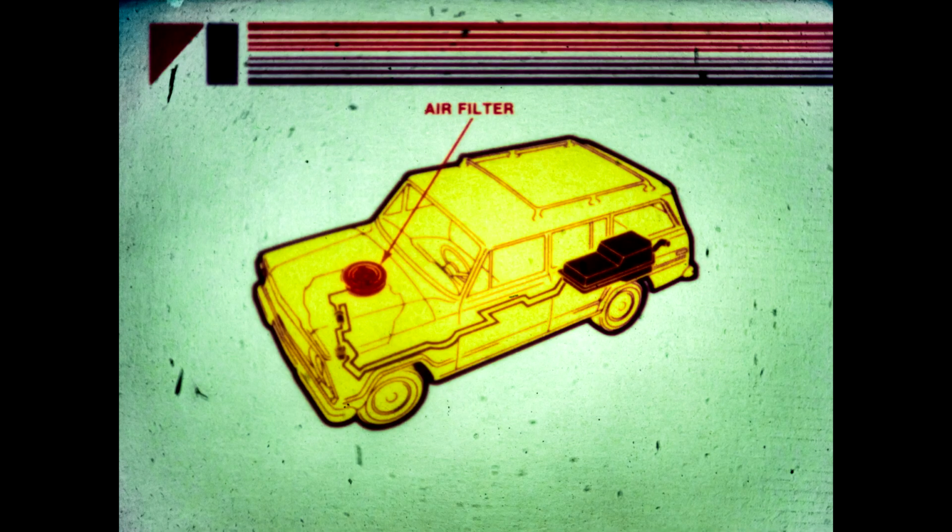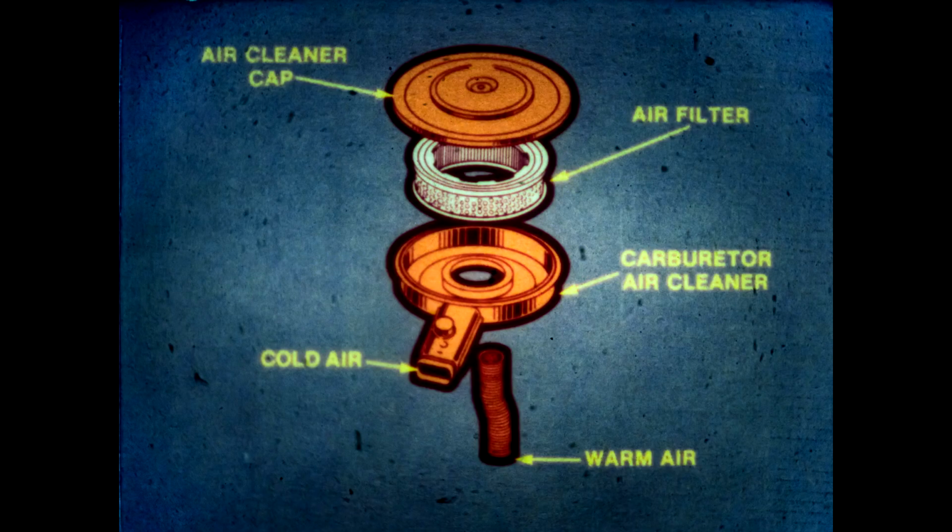The air filter primarily prevents airborne contaminants and abrasives from entering the engine. It helps reduce air noise rushing through the carburetor and also acts as a flame arrestor in case of carburetor backfire. Service is important because a dirty or clogged air filter will restrict airflow, causing performance and fuel consumption problems.